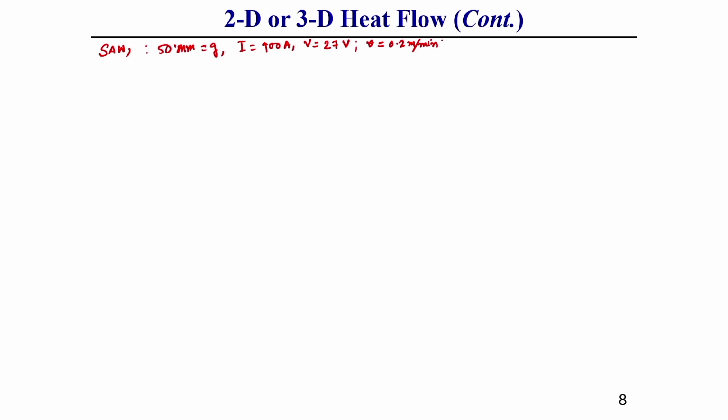By using the above equation, with density 7850 kg per meter cube, and your T actual, which we are considering, which is actually your nose temperature 550 degree centigrade, and room temperature T 0 equal to 25 degree centigrade, it gives us a G bar value which is equal to 0.88.